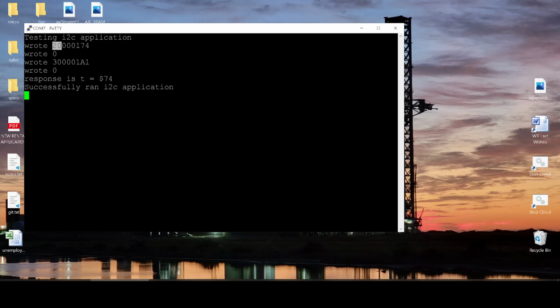This would have been, in essence, the command message, but since it's pretty much the same every time, I utilized this to tell me to set a write or read bit, since on a read you send a write message. So I used that to send a write and read bit, and then another bit to say whether it's valid or not.